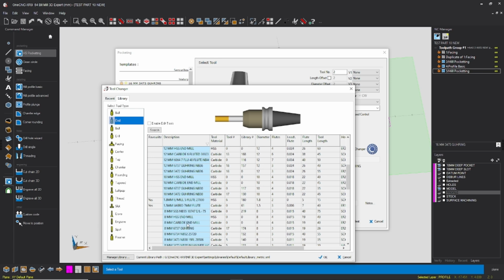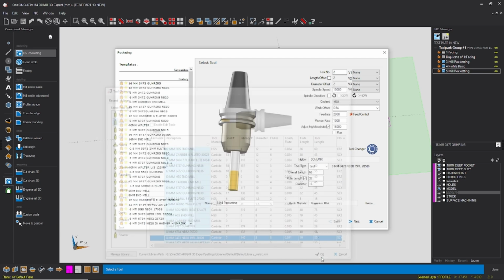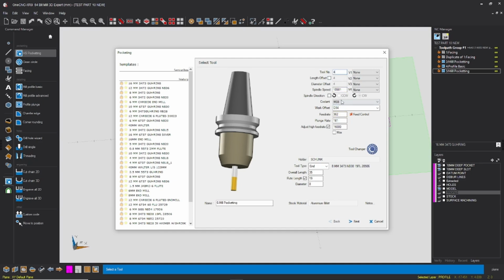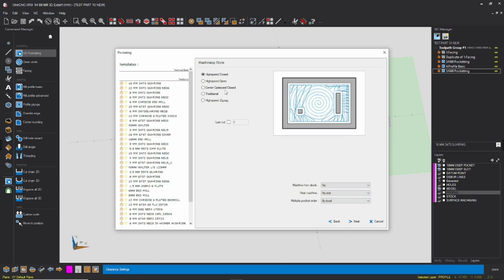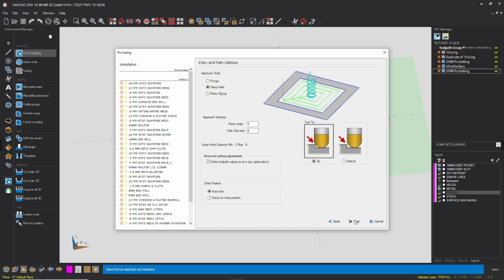Let's find an 8mm carbide end mill. Click that. We'll call that tool 4. Set 10,000. I'll go 2,000 on there, 1,000 on there. We'll keep this at 9.8 for now. High speed close, and now you want to click rest machine, and select that pocket 5. Now it's going to search for everything that hasn't been finished from the 16mm tool. We're going to go ramp helix.